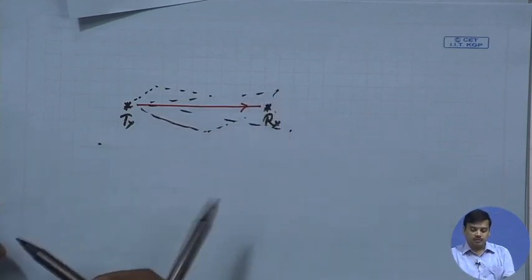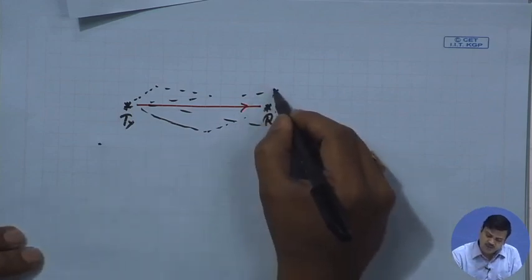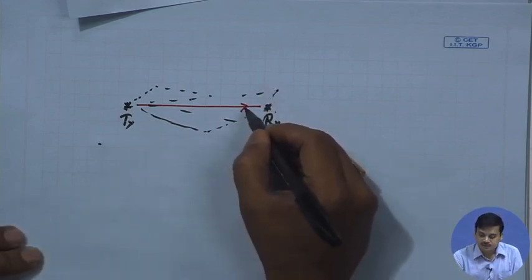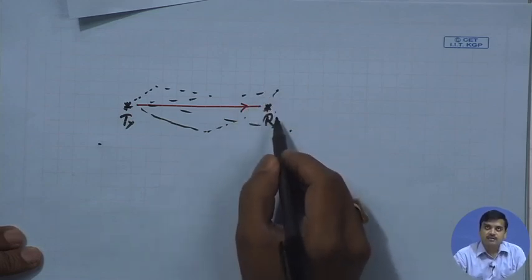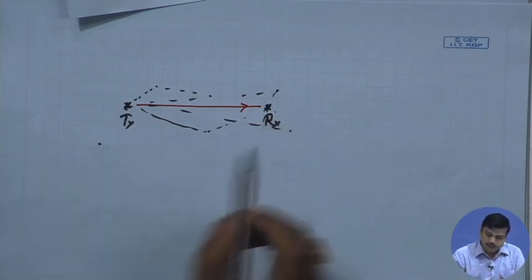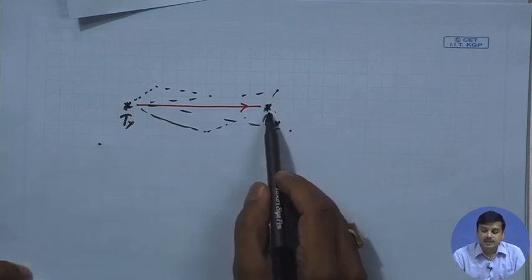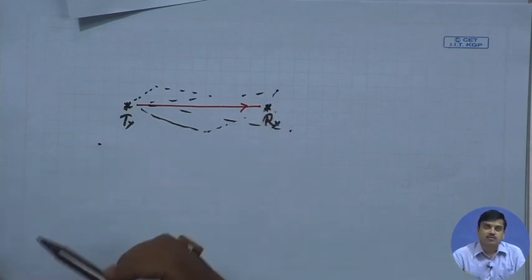In that case, what we have is a Rician distribution, and when these are almost negligible, that means when this is infinite in ratio with respect to the powers in this, there is hardly any fading. So, we said last time you could almost imagine this to be an AWGN condition, if there is only additive white Gaussian noise, or near to ideal condition with a signal strength.